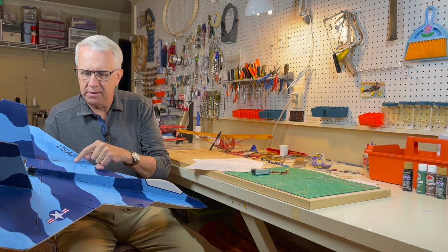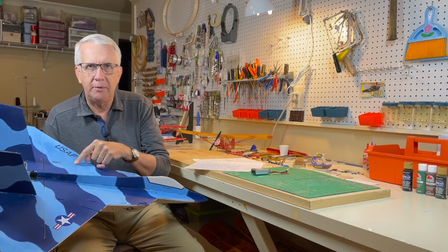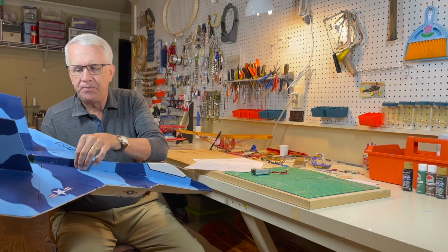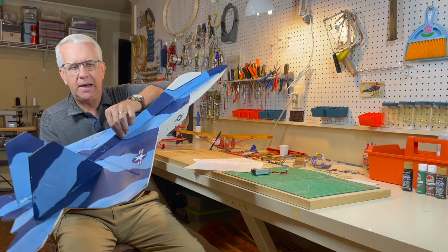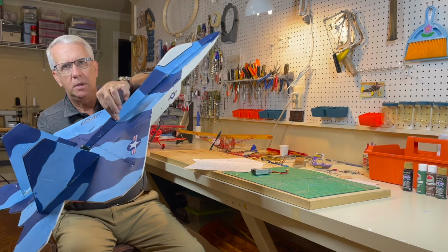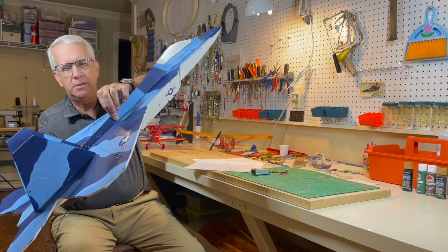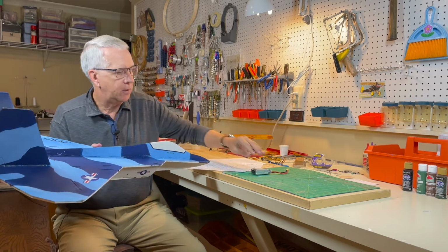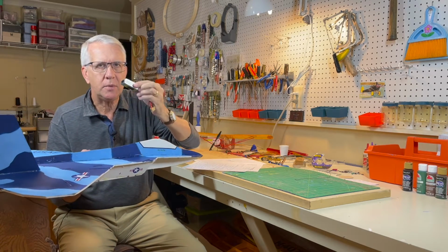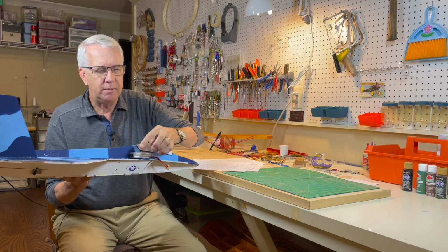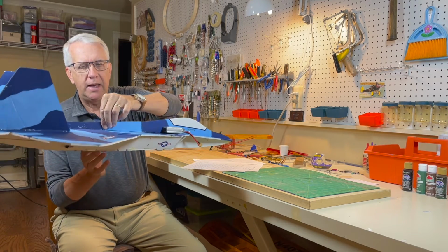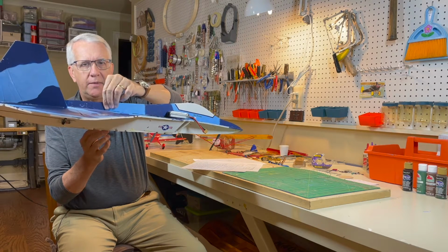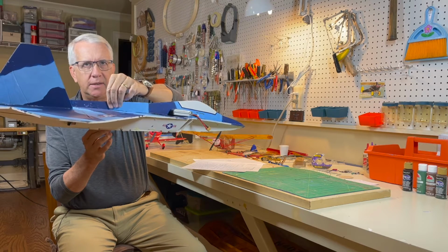And what I did is, while I was constructing it, this joining line between two foam panels to complete the wing is the location of the center of gravity from the plans. So when I say suspended, if I pretend that there's a line or a rope holding this, in this case my fingers, you can see the plane is incredibly tail heavy. That is to be expected with a motor. But what happens on this design is there's a 3-cell LiPo in the battery compartment down below. And when I hold it at that point, you can see the battery adjusts the weight so the plane is level when held at the center of gravity.